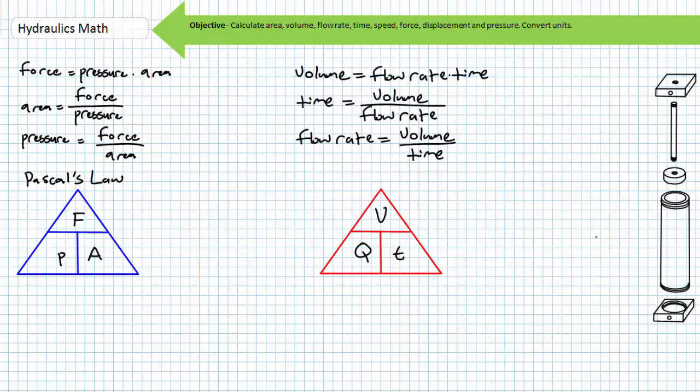We are only a couple minutes into this lecture, and a quick scan of the units used to measure pressure and flow rate tells us that pressure governs force, and flow rate governs speed. Equally as important, it also tells us that pressure has nothing to do with speed, and flow rate has nothing to do with force.